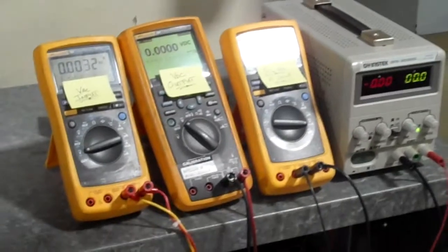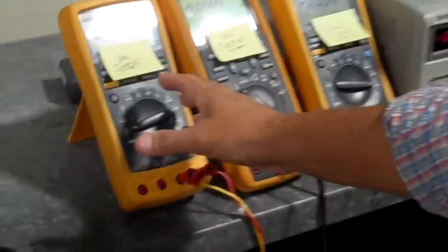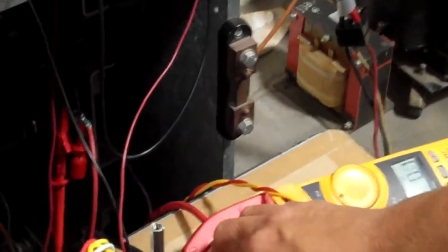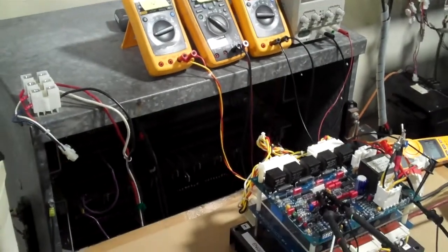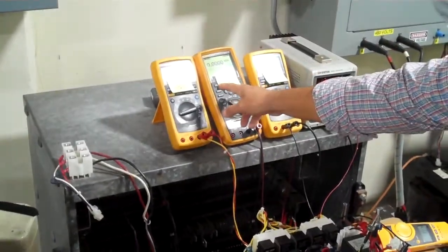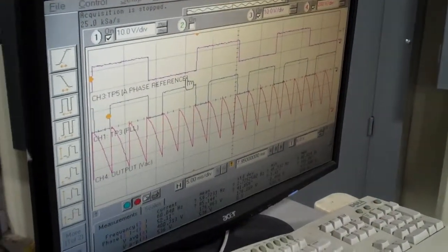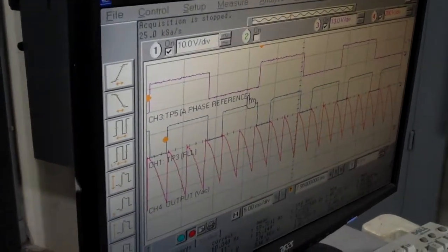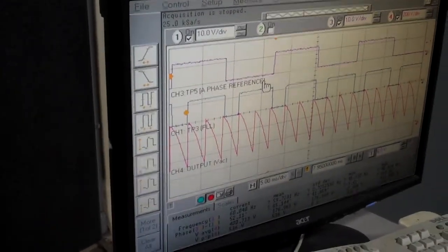For this particular video, we're going to bring in 480 volts from the wall. It's going to come here through our SCRs. We're going to rectify that signal, and it's going to go through our load bank, and we're going to get approximately 14-15 amps. And here's the DC output. We're going to be looking at the delay angle as a function of SIG HI and the corresponding DC output, keeping in mind that the application for this customer is to be around 400 volts DC.